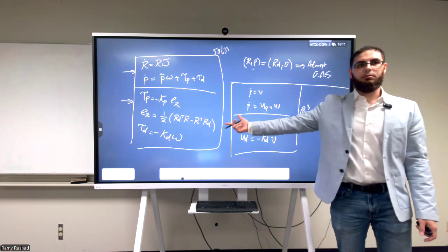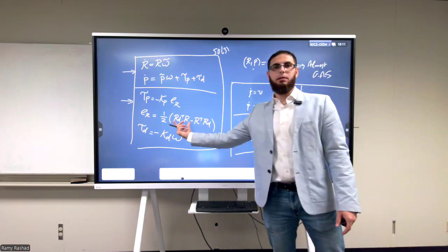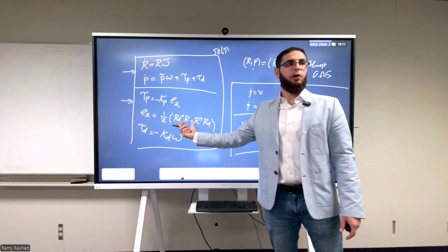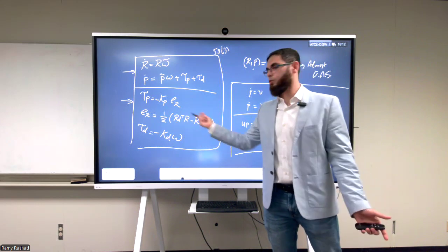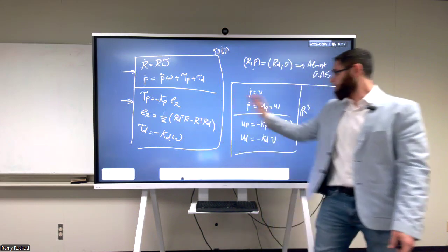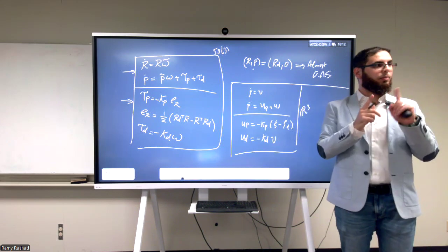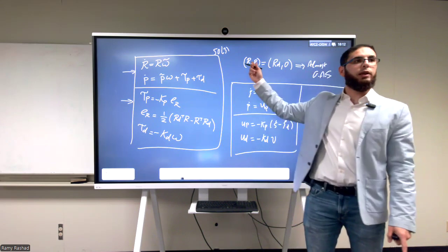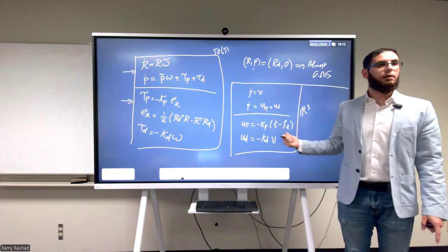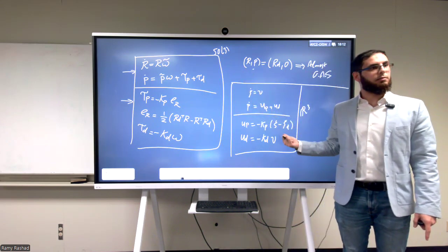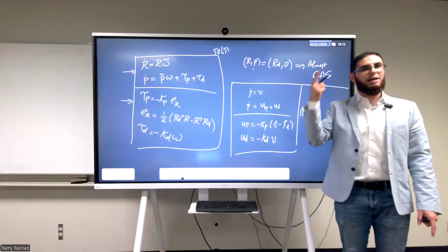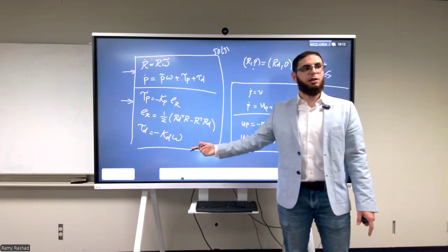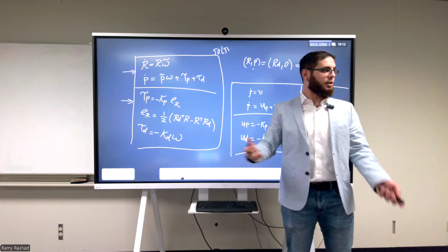The complication of this comes only from the fact that we have a potential function on SO3, on a manifold. This is the only complicated part. But there's another thing that's complicated also: the fact that this closed loop system has 4 equilibrium points, which was never the case here. Because in fact, this is a linear system, and we said before, if you remember, linear systems have only one equilibrium point, which is the origin. Here I have 4 equilibrium points, which has to do with the geometry of SO3.